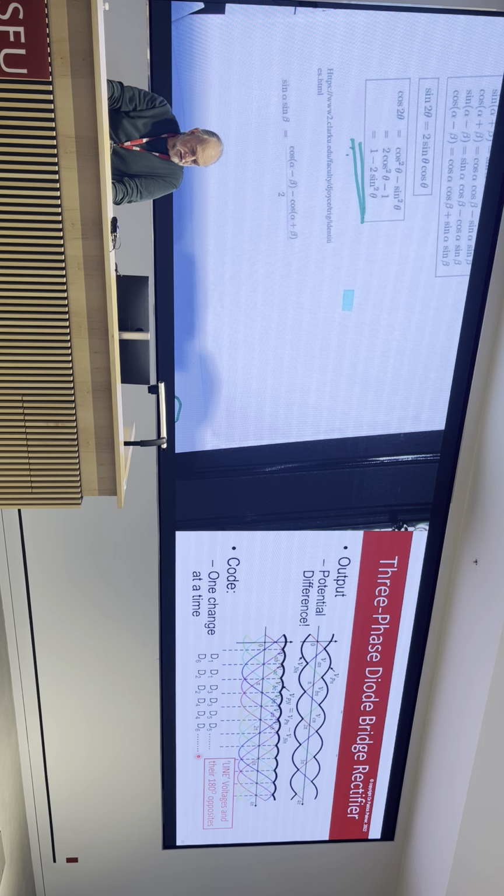Do it with respect to the simulation. Notice the coding: six different unique codes down there. 1, 6, 1, 2. So notice the D1s are on for a third of the cycle, the D3s are on for a third of the cycle, the D5s on. Same at the bottom, but displaced by 2. So that's quite an interesting dance.